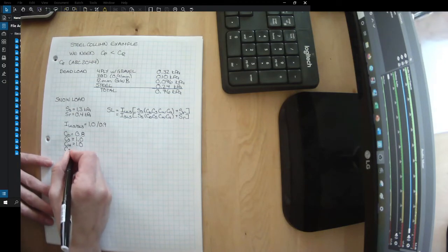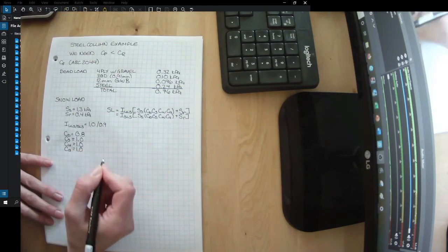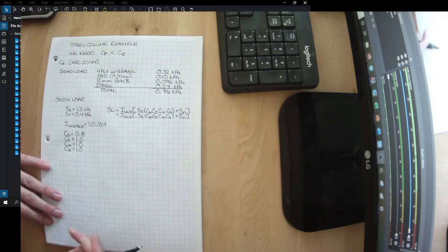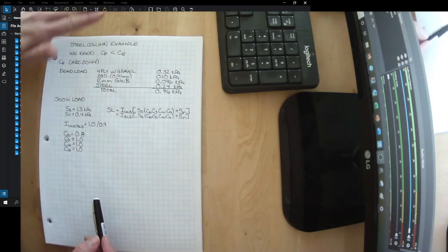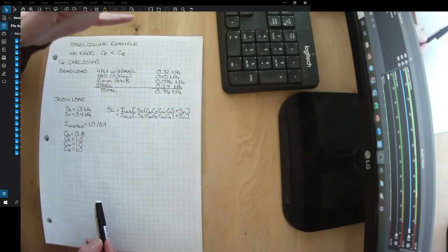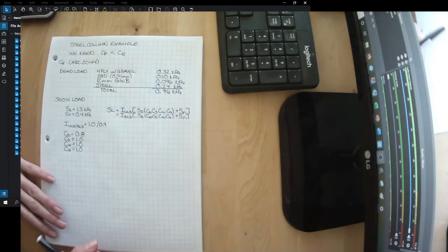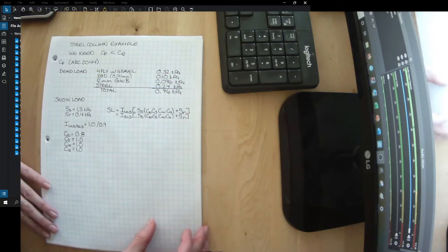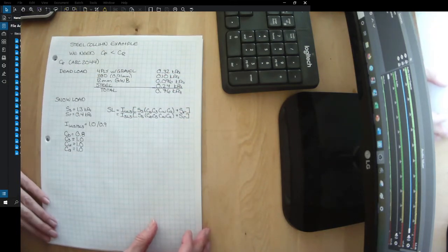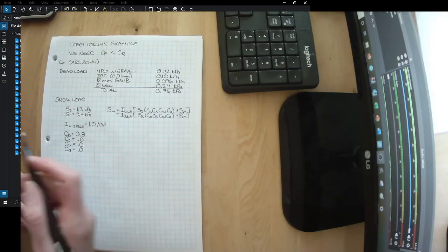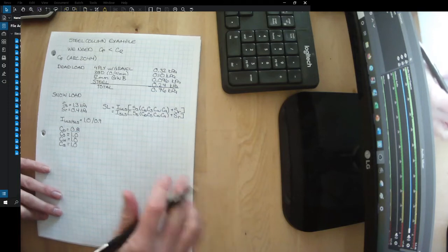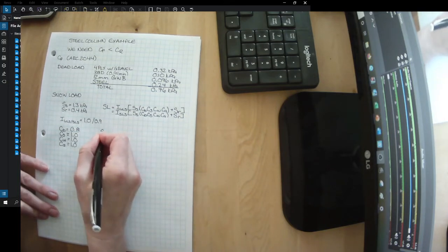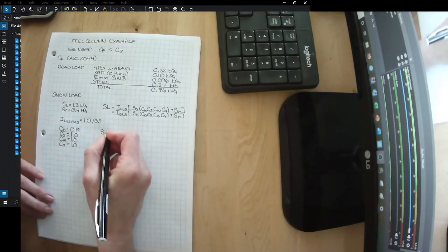And then we have our snow accumulation factor, or our accumulated snow load factor. We have a flat roof beside another flat roof at the same height. So there's no snow coming off and falling on that lower roof. So we don't have an accumulated snow load factor. I also told you guys I wouldn't give you any problems that had an accumulated snow load factor. So it looks like we can calculate our snow loads.